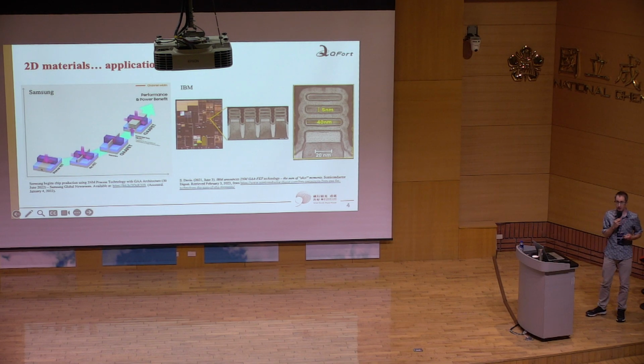At first, that scaling, or reducing of transistor size, was basically through reducing the size of the transistor in this traditional planar FET structure, making them thinner and narrower. But you start to run into problems, particularly with silicon materials, where if it's too thin, your interface starts to affect the carrier transport.